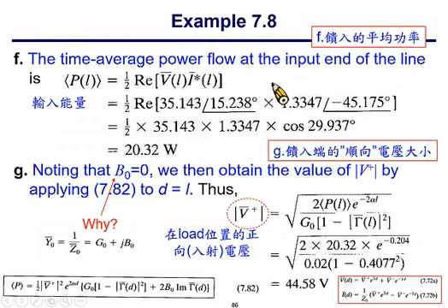which means this equation can be greatly simplified by neglecting the very last term. You only need to worry about this one, gamma D, and G sub 0, which is essentially the real part of the admittance. Because the characteristic impedance is 50, G sub 0 is 0.02, the reciprocal of 50. Then 2 alpha D: we already have the alpha value just now. In fact, you just plug these values in. So V plus